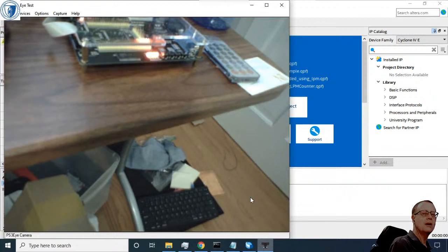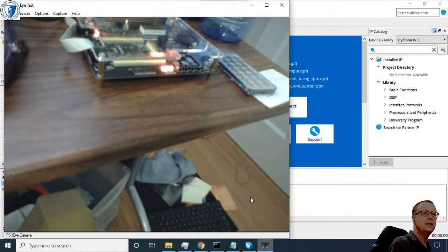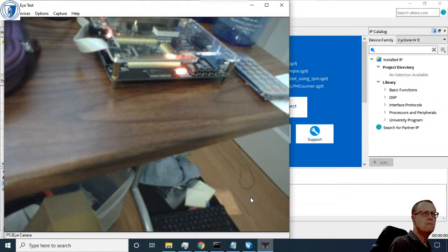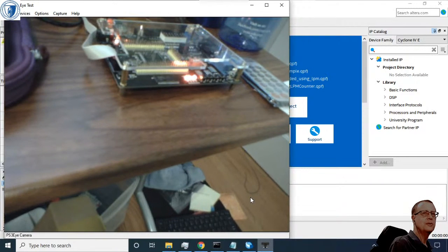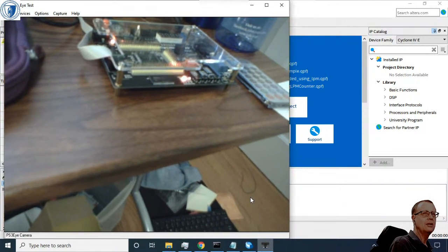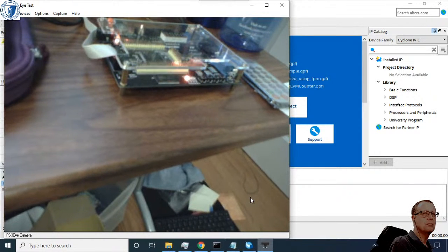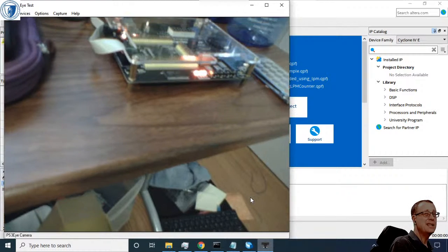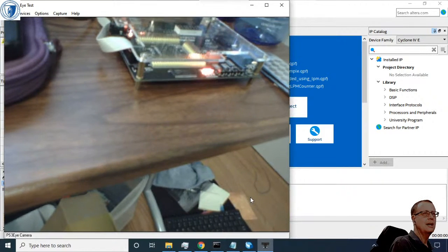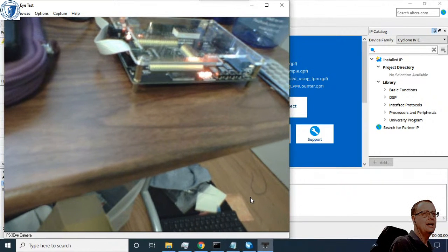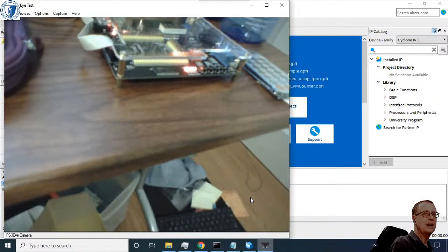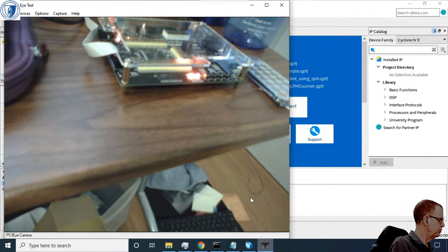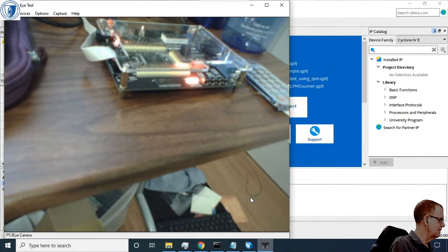And what I did, in the example in the video, I made a divide by 50 million counter, so a modulo 50 million counter, and I just took out pin 25. I think it was 25 down to pin 0, so it was the 26th pin, the most significant bit pin, and I pulled that out and connected it to the LED on the left hand end there. So that LED is now blinking at a 1 Hertz rate.